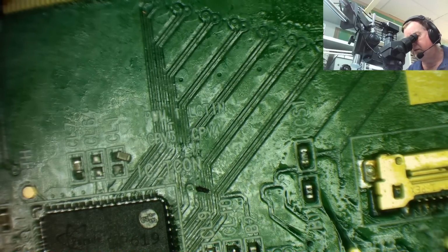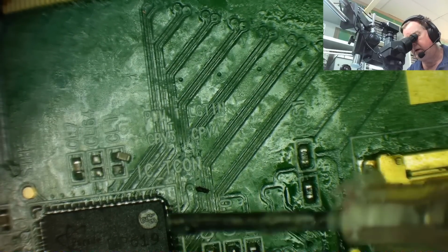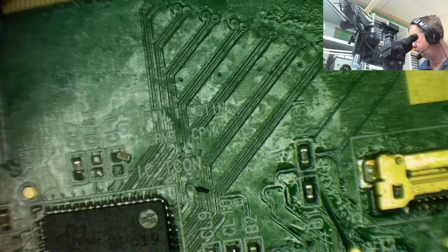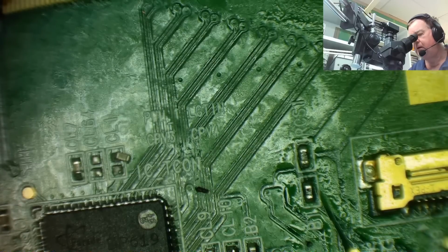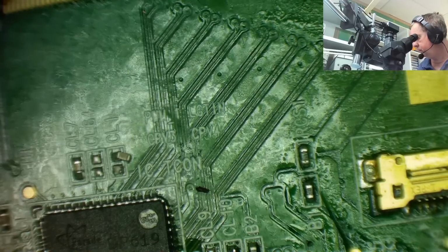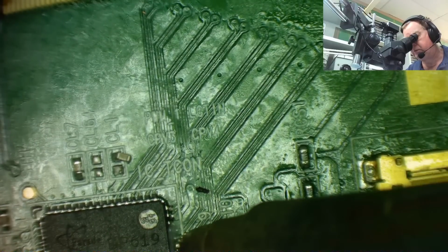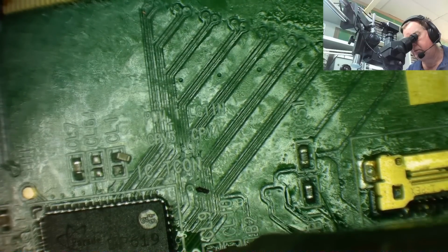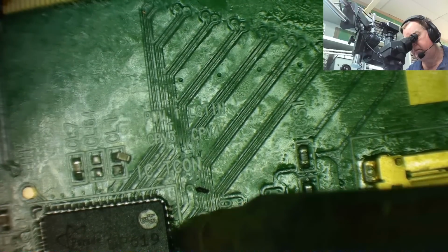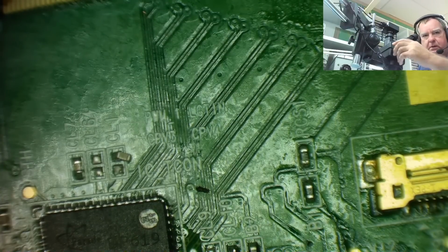I'll just try first and just get it to. No, I'll put some flux. At the end of the day, everything works better with flux. Get a bit of flux in there, and just get in here and just try to clean up. So I've got no solder on the tip now. I'm just heating that bit. Okay, let's see if that's cleared that up.